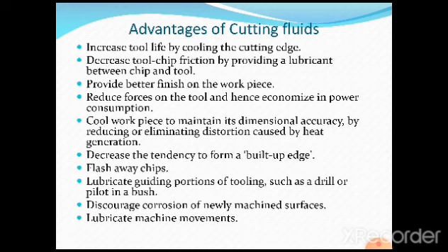Provide better finish on the workpiece. Definitely it's going to provide better finish, because we are going to protect the cutting edge of the cutting tool, thereby reducing the amount of heat generated. Reduce forces on the tool and hence economize in power consumption. It also reduces the forces and economizes in power consumption. Means what? Because with more heat, there is more power consumption, because of loss of cutting ability of the cutting tool.